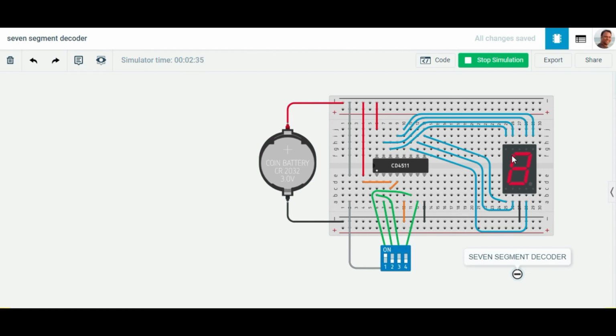If you get a proper 8 formation, it means all the LED segments are proper. If it is not giving the full output, or not providing output 8, it means either the circuit connections are not okay, or any of these segments may be damaged.